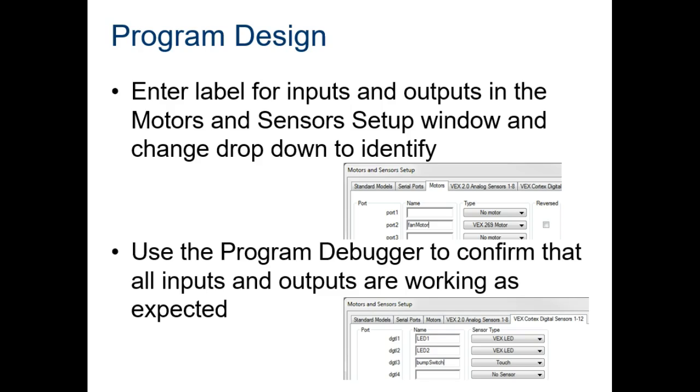It's also important, before you start programming, that you check your labels and use the debugger to make sure everything is working properly. It's really frustrating to get into a program and think you're receiving input from something, and then figure out about halfway through that it's plugged into the wrong socket and not seeing anything, so you spend a long time debugging something that was very simple to fix.